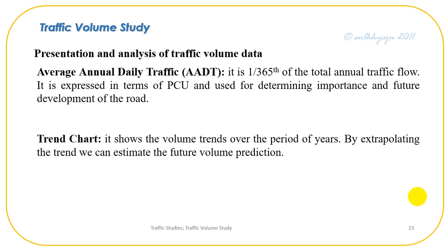Average annual daily traffic, that is AADT. The traffic volume data can be represented as annual average daily traffic. It is 1 by 365th of the total annual traffic. It is expressed in terms of PCU and used for determining importance and future development of the road.